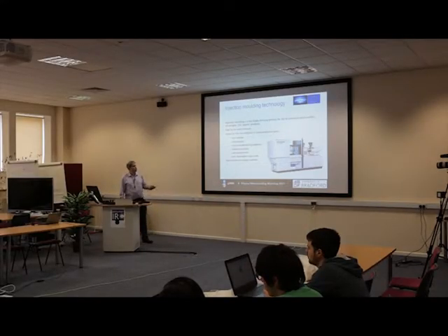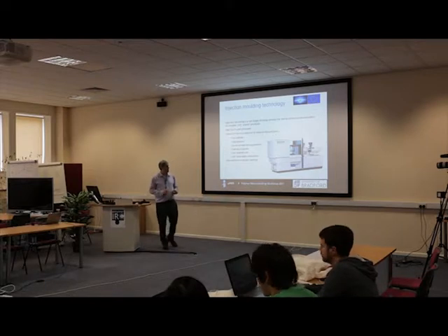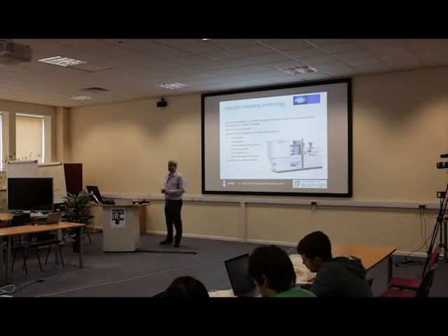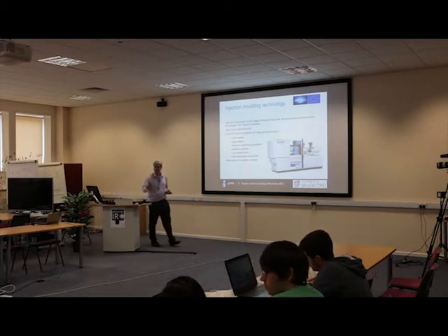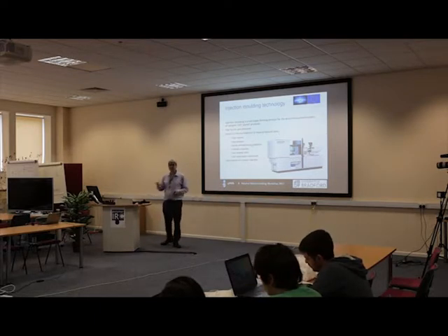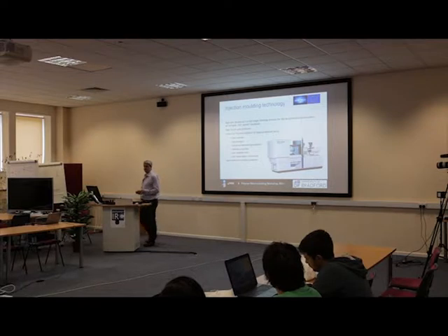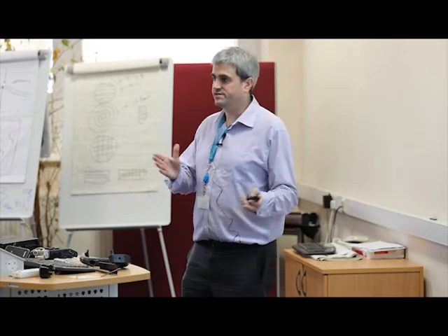Historically, these were always hydraulic machines in order to deal with the very high forces that are required for this manufacturing process. But recently, since, say, the mid-1990s, there's been a big shift towards servo-electric driven machines because they offer a much higher precision, almost like CNC precision and control. They also use less energy than the hydraulic machines for the majority of components. So even though they cost a little bit more, there seems to be a general trend moving that way, particularly with the increased cost of energy.